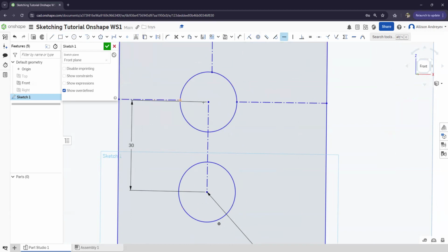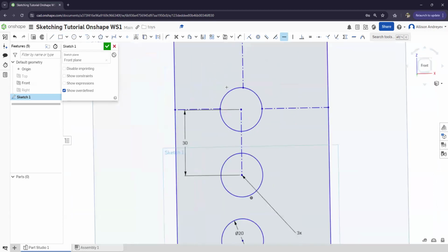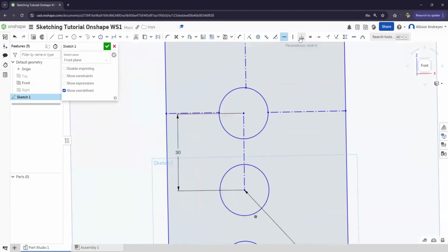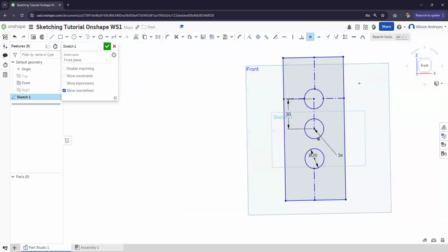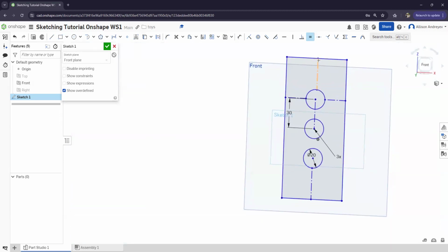say, I'm just going to click the horizontal feature here. It looks like they're both horizontal. And I'm going to then use the equal symbol again. So equals this line and this line, and there we go. So now we have a pretty even traffic symbol, but I think it's a little bit tall.